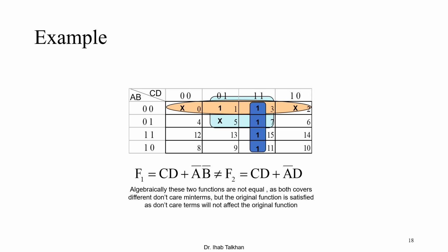And here I can give you an exercise to do at home. You need to design a converter, decoder, or encoder, which means you need to convert BCD to XS3, XS3 to 2421, 2421 to 8421, and so on. You can do this exercise by adding, for the BCD, cells number 10 to 15 as don't care, or any undefined states as don't care. So you have an exercise at home to do whatever conversion, for decoder, encoder, and converter. Do that at home and let me know what you ended up with.